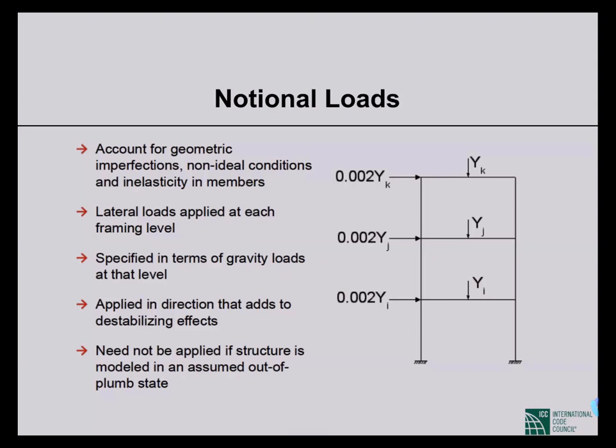They need not be applied if the structure is modeled in an assumed out of plumb state. So if we model the structure in the out of plumb state, then we don't need to apply them. But usually we don't model out of plumbness, we apply these notional loads.